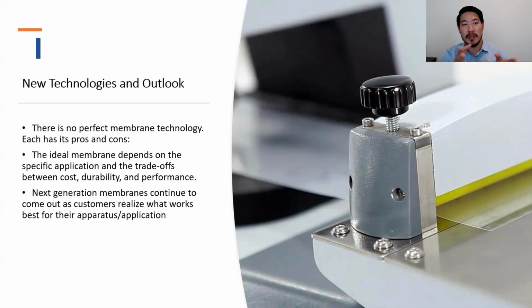Yeah, definitely. The technology is going to continue to advance. The hydrogen economy is going to continue to grow. Currently the technology prefers PEM, the proton exchange membranes, but we do see that in the future, anion exchange membranes will be preferred. As we scale up, the precious metals needed for a proton exchange membrane are going to be hard to get. So in order to scale up and make it economic, you have to take the best of both worlds from alkaline and PEM and use AEM. That's where we think we'll be going.